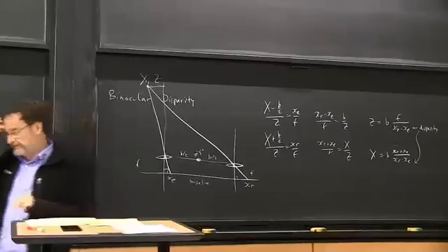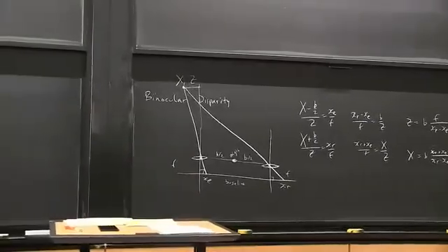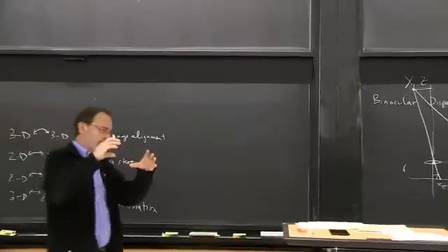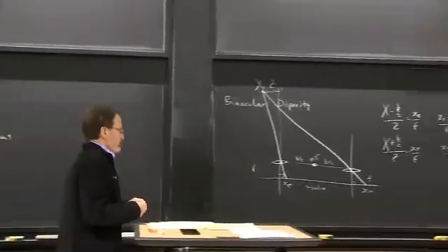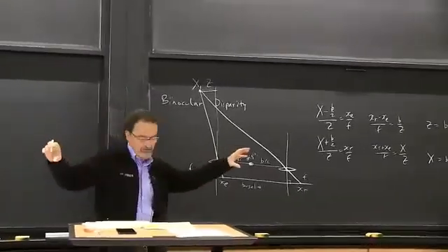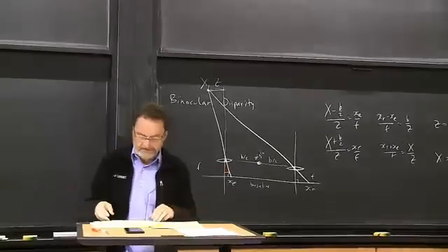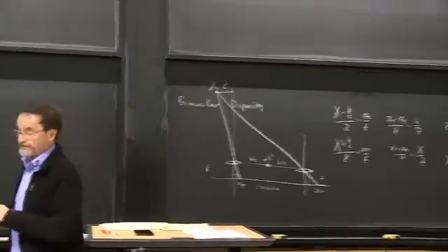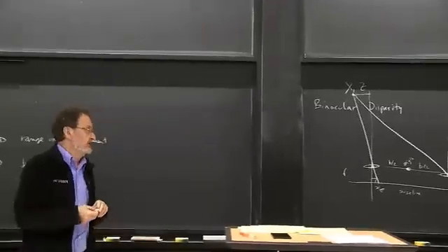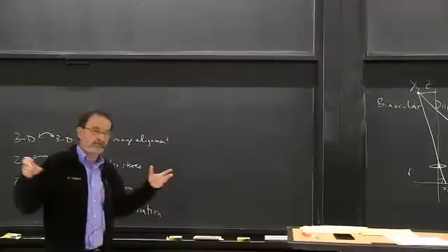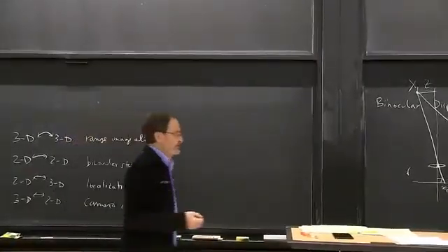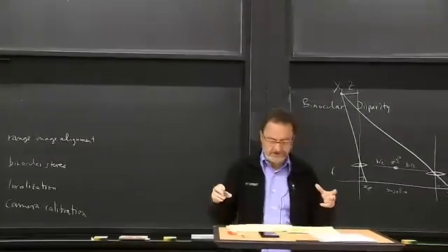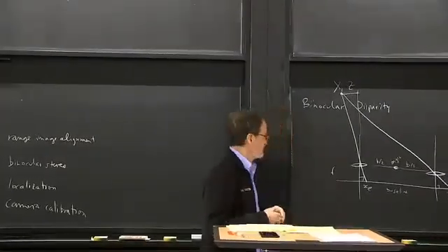So, for example, in autonomous vehicles, it'd be nice if the two cameras could be close enough together so you could hide them behind the rear view mirror rather than have them go all the way across. And if they are that far apart, then you have a calibration problem, because they're unlikely to stay perfectly lined up over the lifetime of the car. So you'd have to have some automated way of rediscovering the relationship between those two coordinate systems.